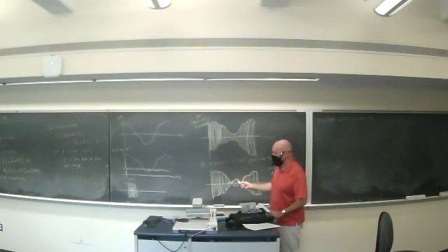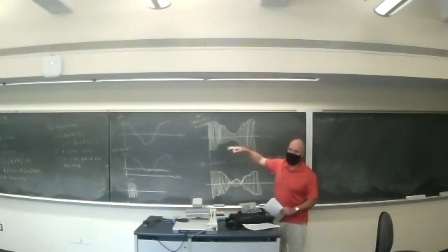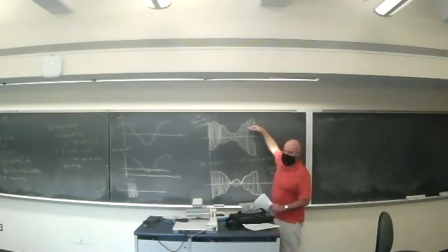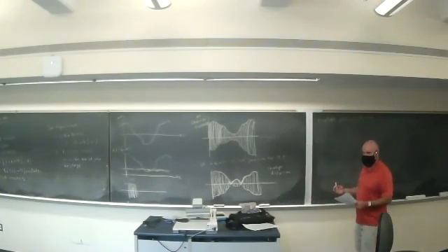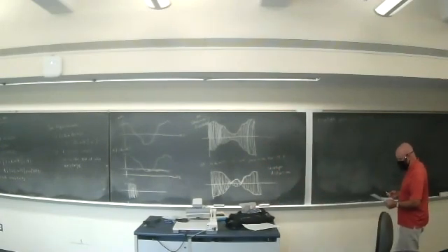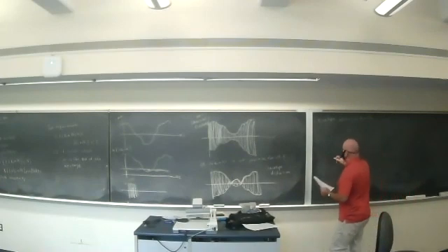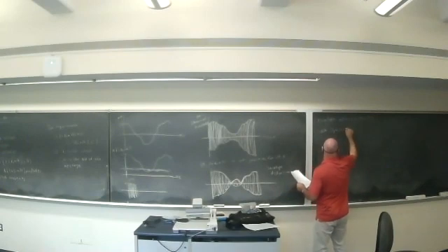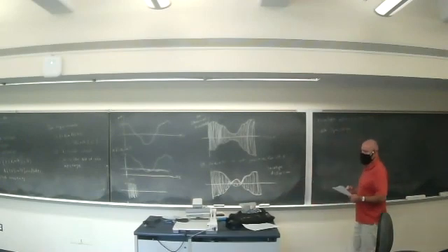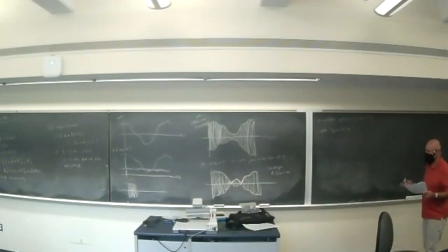And here, that's not what we want. We would like our envelope to be a shifted version of our message. We still have the DC shift here, but that's easy to remove with a DC blocking capacitor. So that's what it looks like in the time domain to the best of my artistic ability, which is not much, but again, we'll get a chance to see these things on oscilloscopes and in MATLAB.